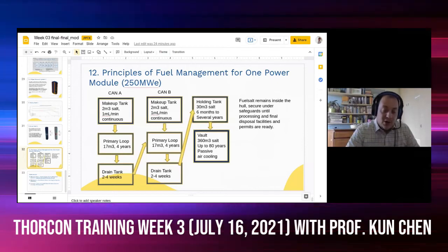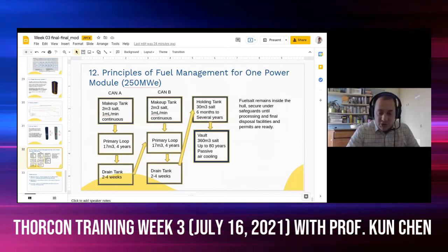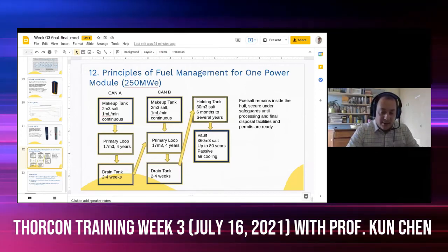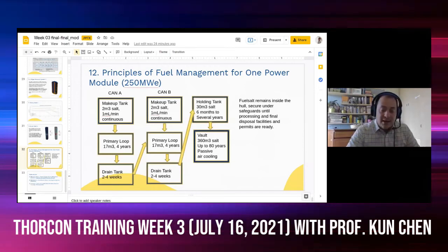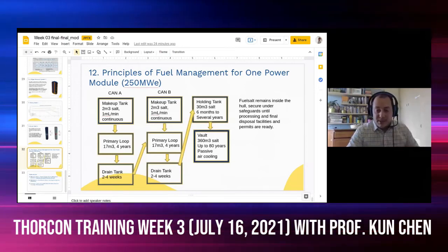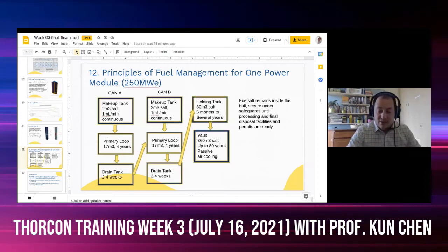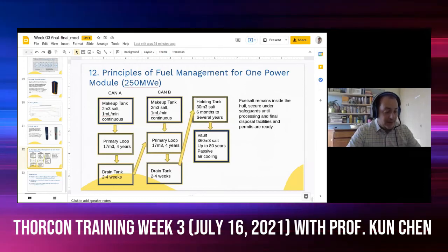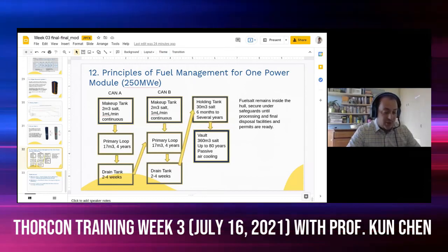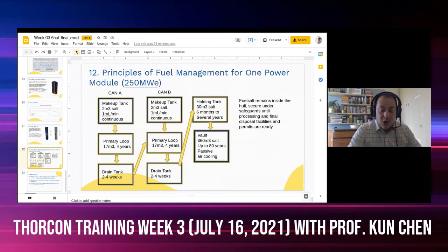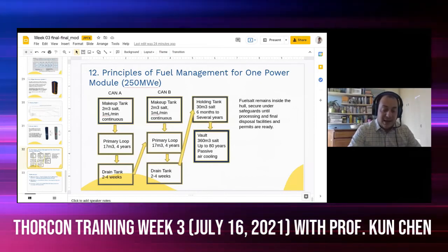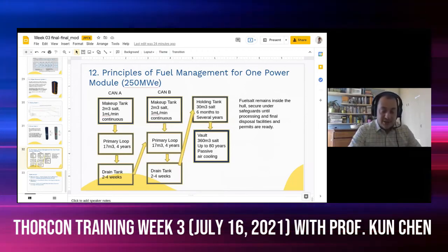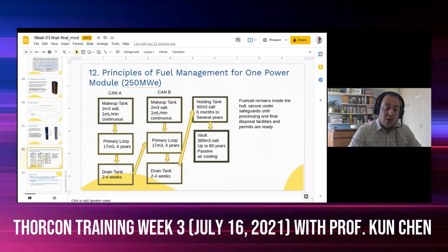In a fast reactor, the average neutron prompt lifetime of around 1 microsecond makes the increase in power so fast that the effect on the compressibility of the fuel due to the presence of gas bubbles does play a role. Specifically in the European molten salt fast reactor, there is an active introduction of bubbles inside the core for different purposes. In that specific case, yes, there is a need to model two-phase flow for specific accidents.